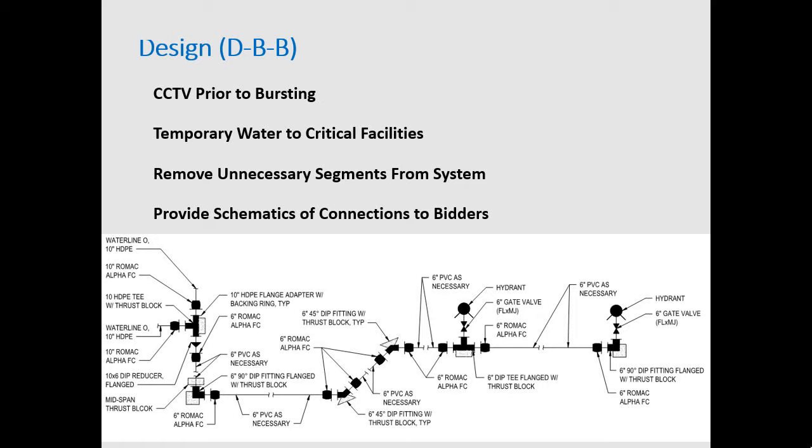The other thing we did was the temporary water, especially down there at the southeast end. We did provide temporary water designs and requirements to make sure that was there. The design-build contractor, when he did his work, was actually able to phase it correctly in a way that he never had to set up temporary water. Again, that was his local area knowledge, able to perform that work with the owner and the users of the buildings, where the kitchen's open 24 hours a day. They were able to stage it and work on a weekend when there were fewer people and get that done.